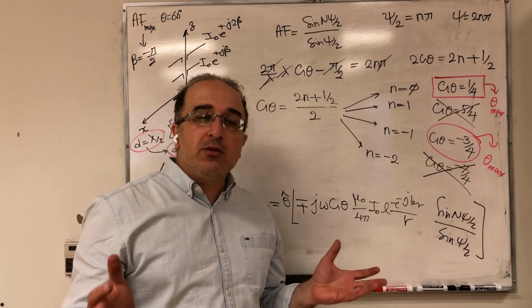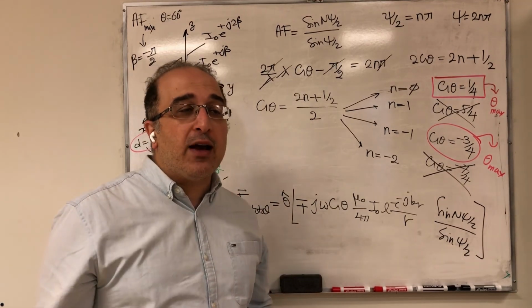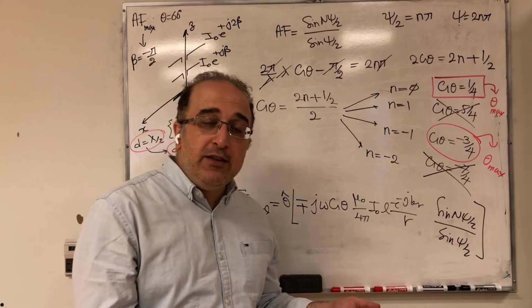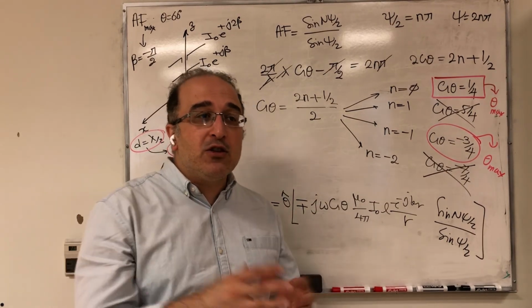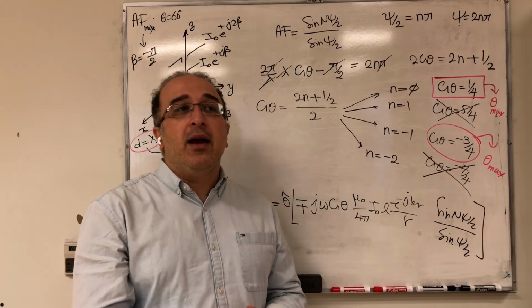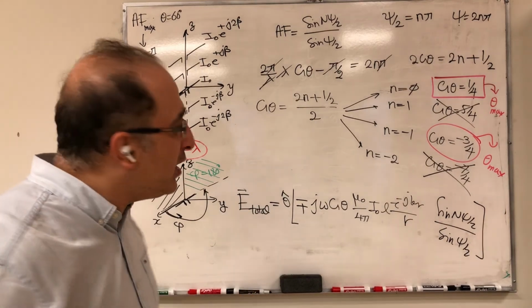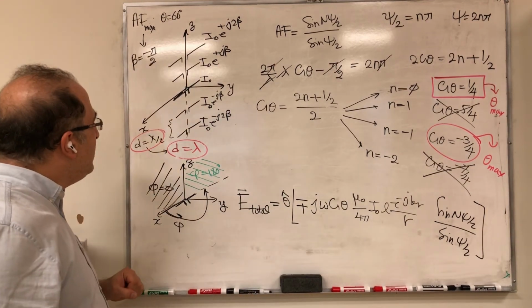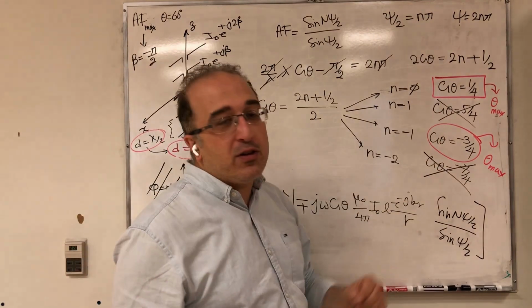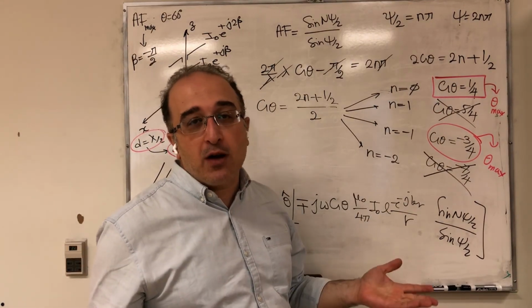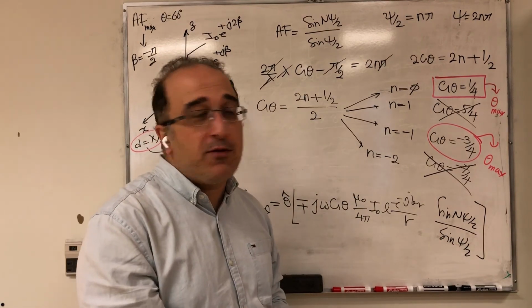So we chose beta to have a certain main beam direction just for the array factor. And then we went to E total, so we needed to calculate E of a single element, and we started multiplying them. And then we also discussed one possible error: after all of this design, if you have the separation different, note that you don't even get the theta equals 60 that you started with, because theta equals 60 was designed based on a separation of half wavelength.